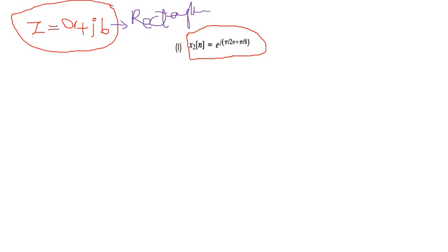You can also express the complex number in polar form. In polar form we say that z equals magnitude and phase. You represent phase like this, e to the j of something. If you compare this, you can see that this is a complex exponential signal in the polar format. When there's nothing here, that means 1 is here, so the magnitude of this signal equals 1.